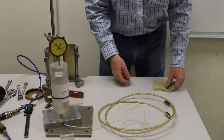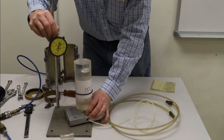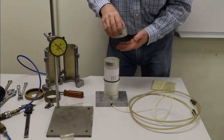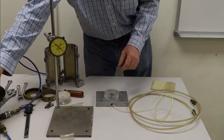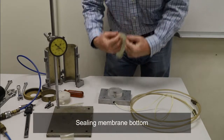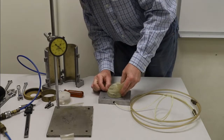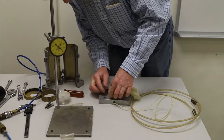So once we have those initial measurements, we want to take the system back to the table, and we're not going to need the top cap for a little while. We shouldn't need the reference cylinder at all for this test anymore. We need to seal the membrane around the bottom cap. I want to make sure it's just one layer, but that it's all the way down.